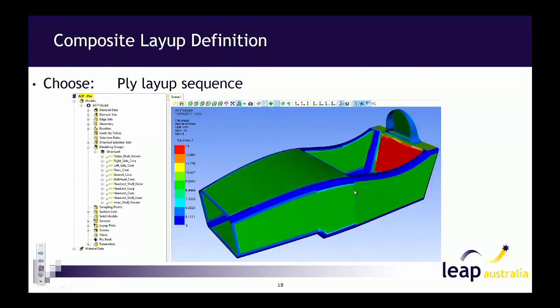Obviously, next thing is you just rinse and repeat. So you build up your structure a layer at a time, different angles within the composite structure. You might be reinforcing areas that are going to see more stresses. You can taper edges. There's a lot of options for you guys to really build up a detailed model.